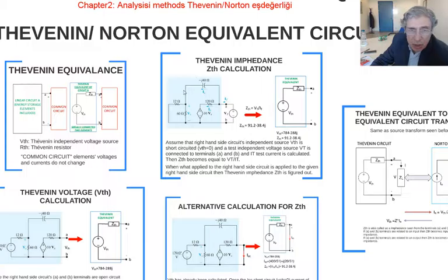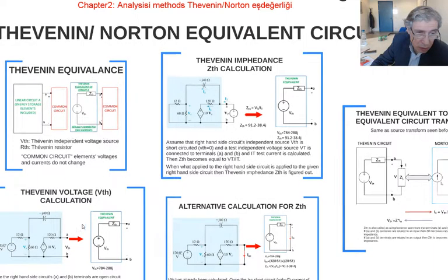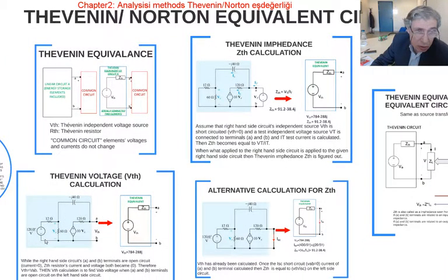So in here, I short circuited the independent voltage source within the circuit given to us. The circuit given to us is this. So short circuit that, apply VT here. So we've got this circuit now. So this is a circuit analysis once more. If I calculate that IT, VT over IT gives me that ZTH. So I know what to do.